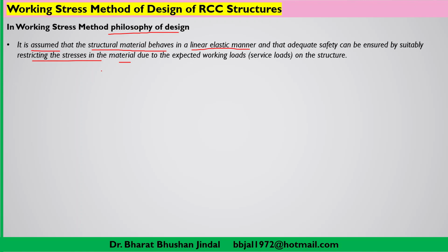So we have to restrict the stresses, or take some reduced value of the stress, so that whatever expected loads, known as service loads, are applied to the structure, they will not fail the structure. It is assumed that the structural material behaves in a linearly elastic manner. This is our assumption in the working stress method.